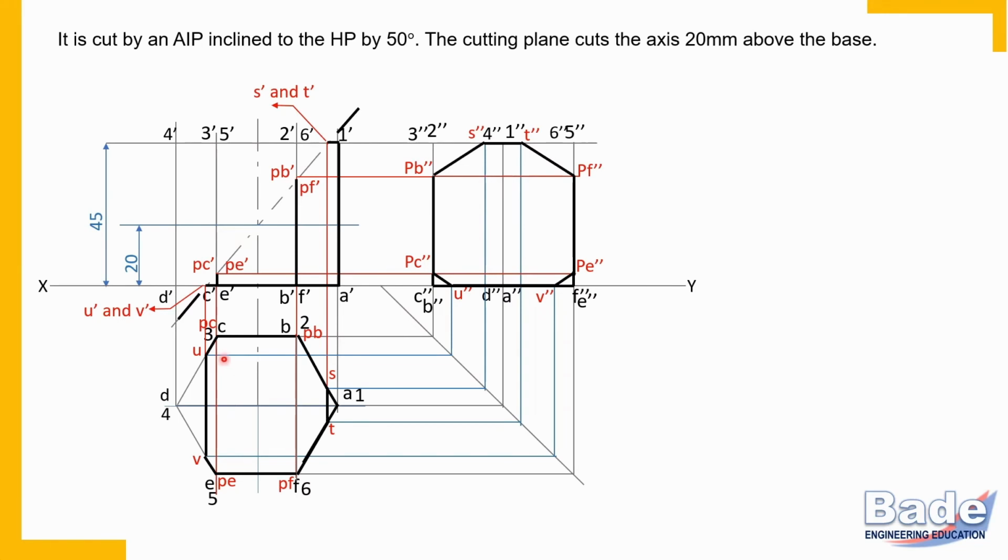In the top view, watch here. After drawing the section, this portion, check it. D4, edge D4 is on the removed side. That means this portion is removed. Check on the left hand side of point CE, this side. It is removed side. So don't make this portion dark. On the right side of ST, it is retained portion. So make this portion retained.